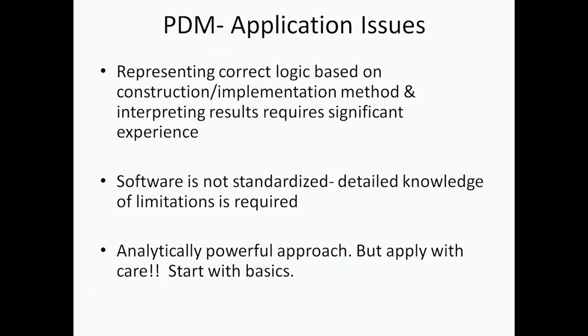Okay, now we come to the application issues. I think I have been repeating this from the beginning, that we have seen a lot of PDM being used, especially through the software that is available. The software that is available today is quite powerful, and we have seen a lot of planning groups use the start, finish with leads and lags quite liberally, but once they do that, nobody is able to interpret what is happening to the project.